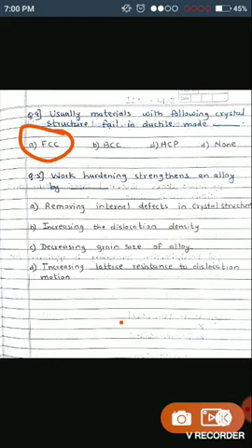One is control of grain size. Then cold working is one type of strain hardening process. Then solid solution hardening and precipitation hardening. These are the strengthening mechanisms. Now if you consider a cold working process and a hot working process, when a metal is worked at higher temperature, let's say above recrystallization temperature, the movement of atoms is more, which implies high strain is produced, so hardness will be lower, right?